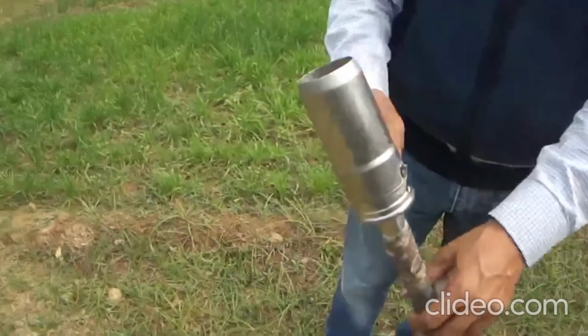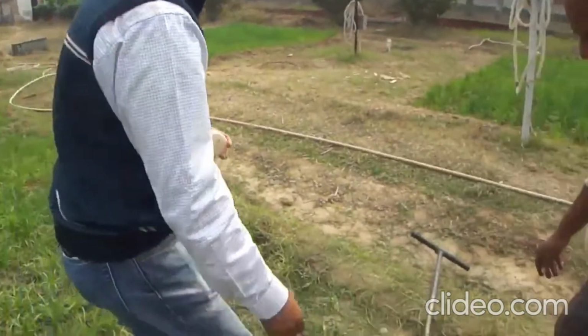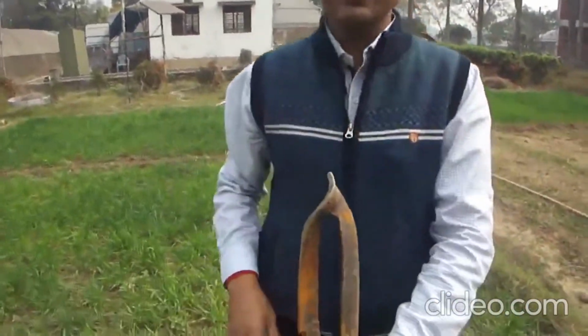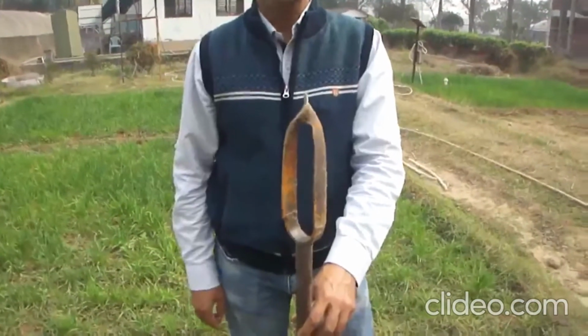However, when we are interested in the hydraulic conductivity or property of soil beyond 15 centimeter, we need to first clear the topsoil layer up to the desired depth and then use this core sampler to collect the sample. How to clear the soil before the desired depth? We have an auger that clears the topsoil first, and then the core sampler is used to collect the sample.